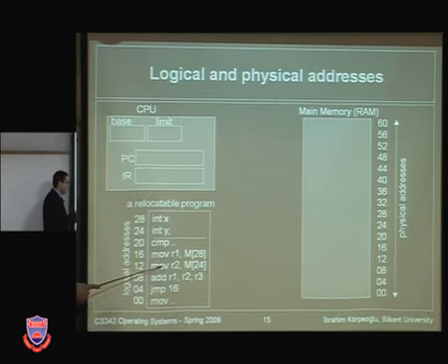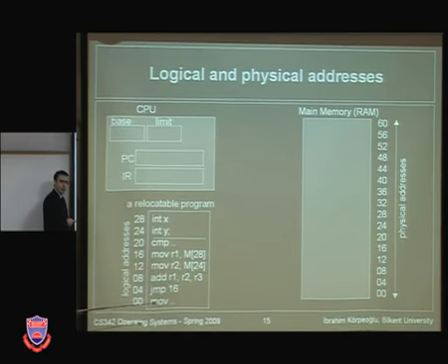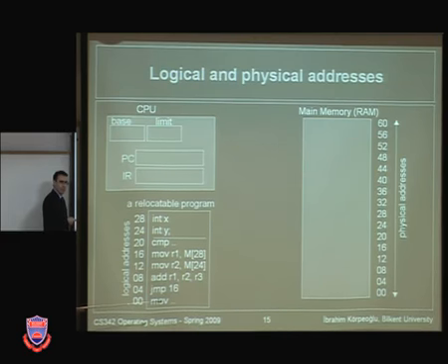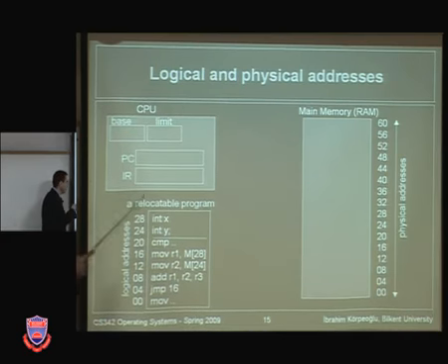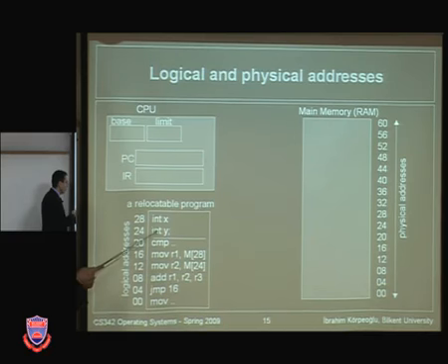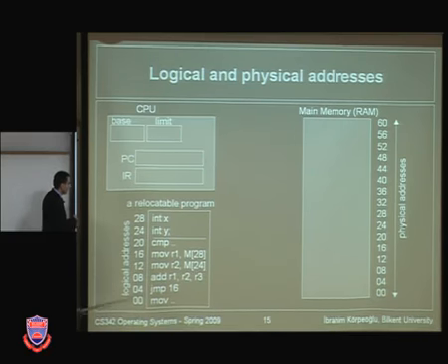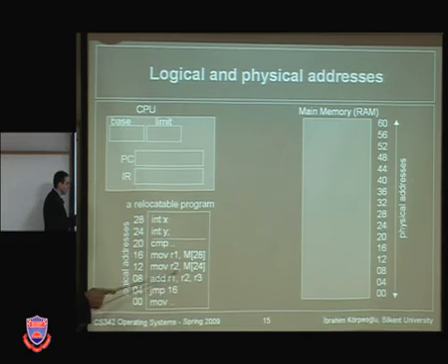In that instruction you want to move into R2 a value. Which value? y. The address of y is 24, let's say, and the address of x will be 28, and so on. So you want to move the value of y into register R2, for example, and you want to add the registers and so on.